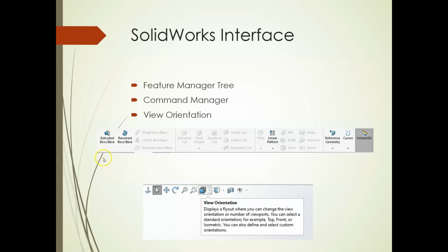The extrude that we're going to be dealing with is going to be the extruded boss base. The command manager is what's going to show up on the side. It's going to be like your browser pane when we're talking in Inventor, but we're going to see that once I switch over to Solidworks, right? One of those other things I didn't tell you about is that you can change the units on the fly in each one of these programs except for AutoCAD.